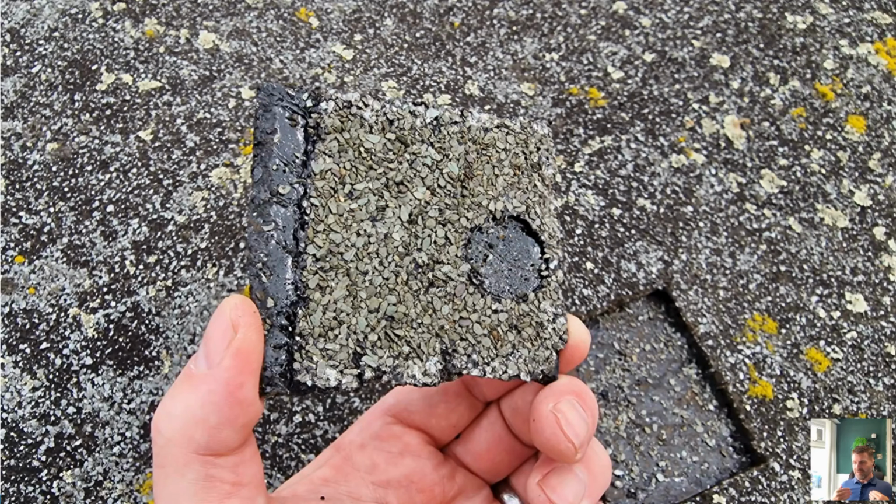So what happens is that layer is loose laid on top of the insulation to allow the insulation to breathe. So the 3G layer with the holes in it is laid, then hot bitumen would have been mopped over the top of that. The bitumen would go through the holes to form a bitumen rivet, for want of a better description, and then the underlay and cap sheet would go over the top of that, so that any vapor or gases coming from the insulation won't cause a blister, because if you fully bond anything to a permeable substrate, it can blister.